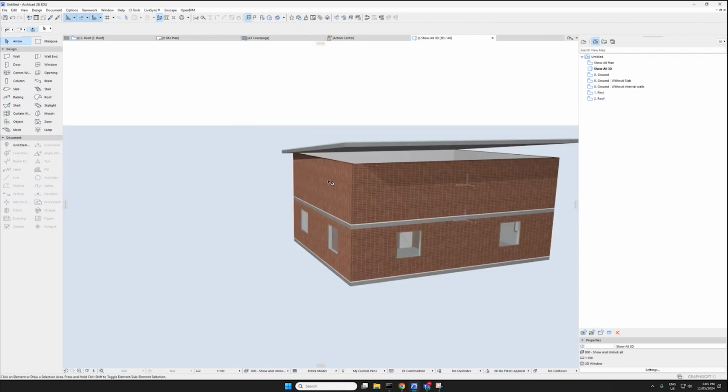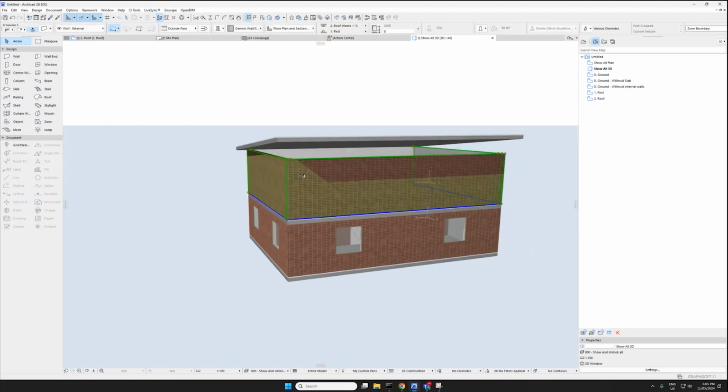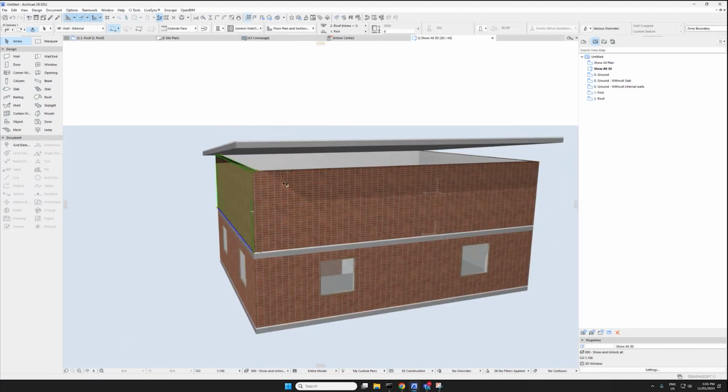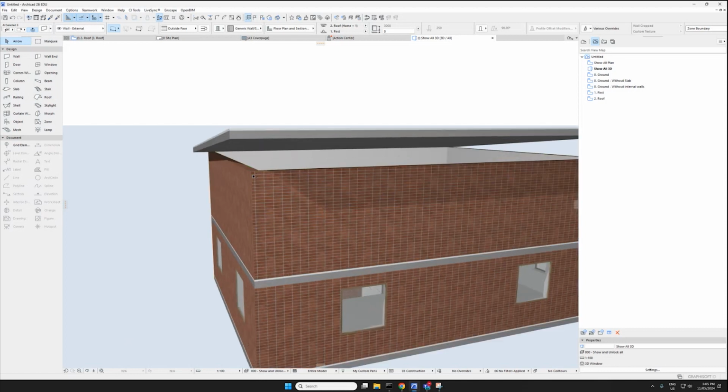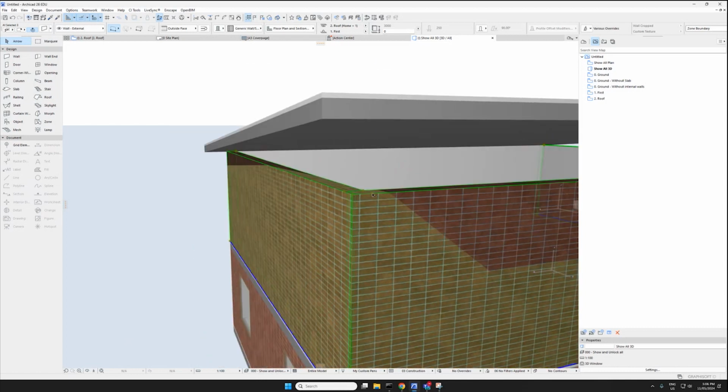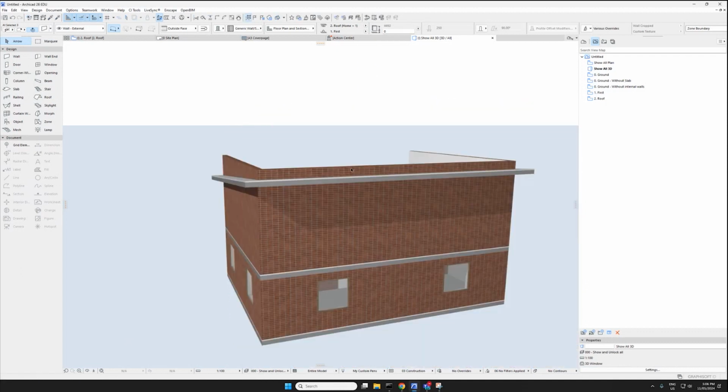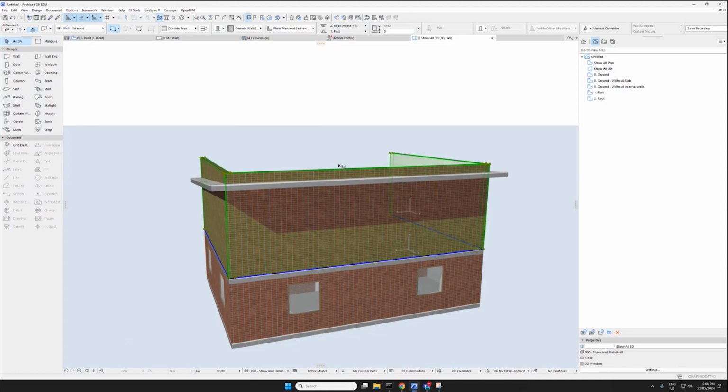Okay, we have the same problem as the gable end. These walls need to extend now. Whether you do it with the same material or another material, let's say we continue with the same material. We can then pull, I've selected these 3 individually, and click on any point at the top. Okay, so we can click up here and we want to stretch it. Stretch it, go. Let's press Control 0. Let's try this way this time, and then crop element to top. We say okay, crop. So now it's cropped.